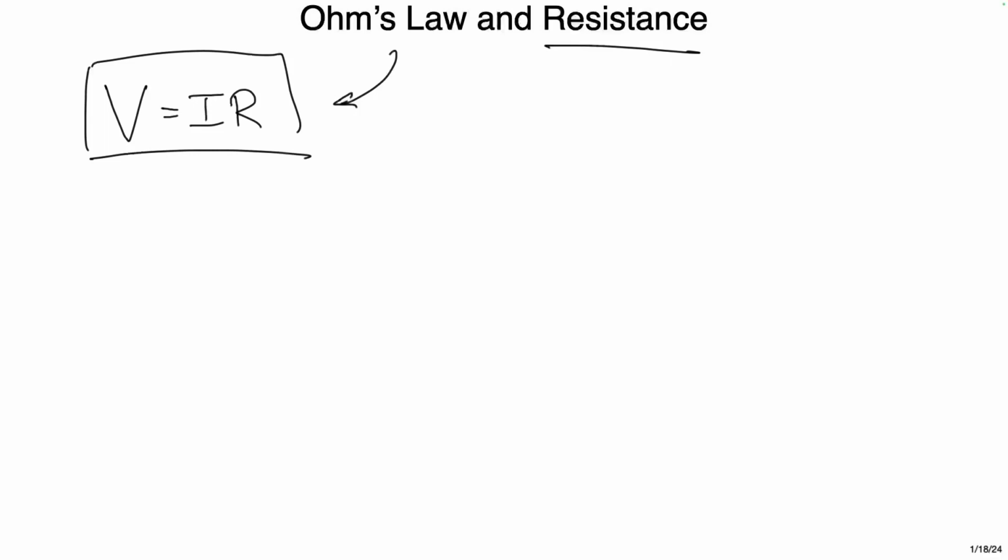So resistance, like capacitance, has a physical measure. That's the Greek letter rho, by the way. It's not density this time. That's the resistivity. It's a number; again, different materials have different constants associated with them, but that's the resistivity, times L over A. So a physical resistor can have a length and a cross-sectional area. The longer you make a resistor, the more resistance it has. The smaller you make its cross-sectional area, the more resistance it has.